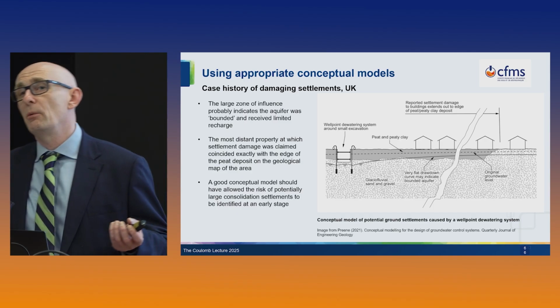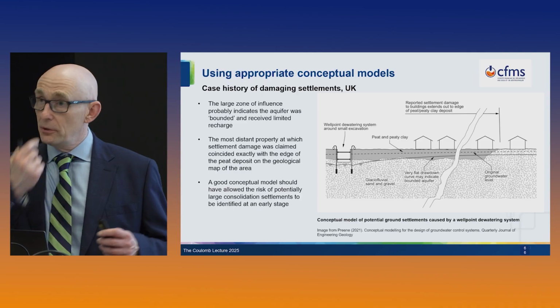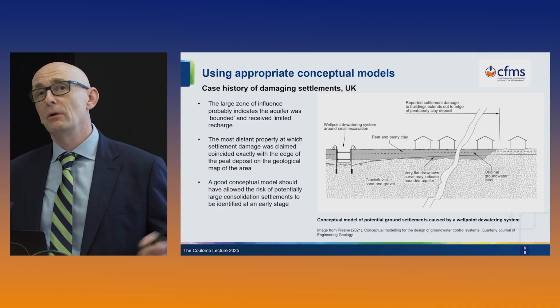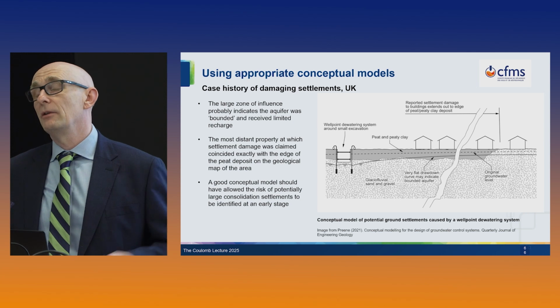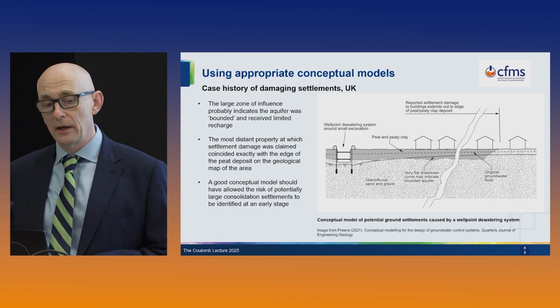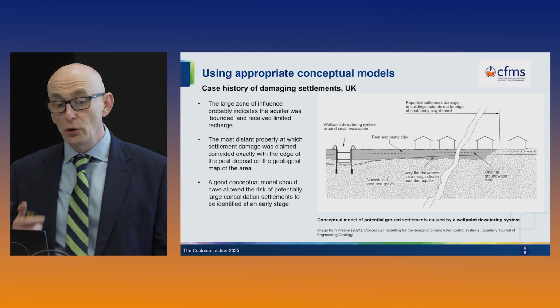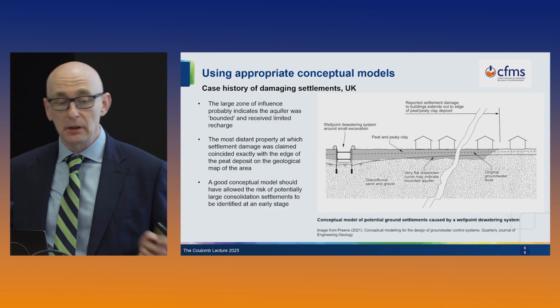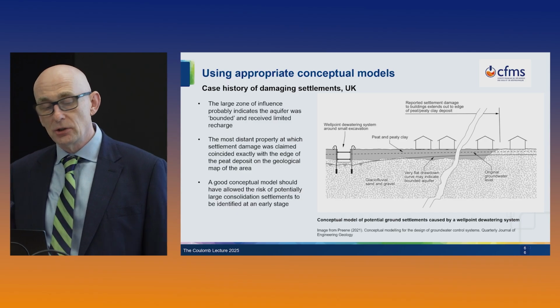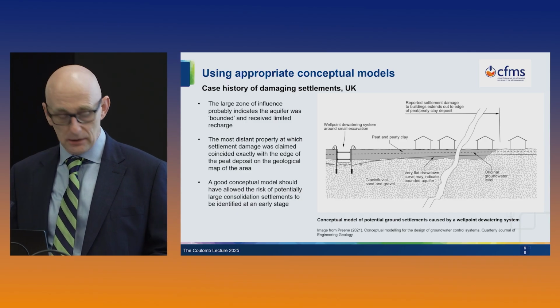In the UK we have the British Geological Survey, which produces maps of the area. So you could argue that without drilling any boreholes on site, the geological mapping that was available in the public domain should have directed people towards possibly figuring out that there was a problem. And I think a good conceptual model, or in this case any conceptual model at all, given that I don't think one existed, would have allowed the risk of potentially large consolidation settlements to be identified at an early stage.